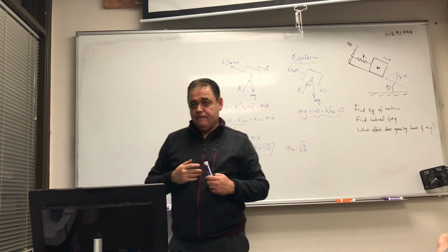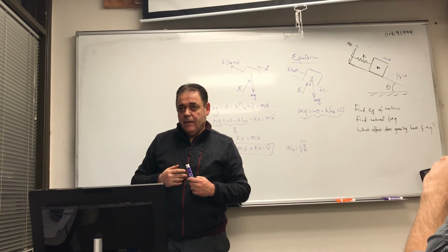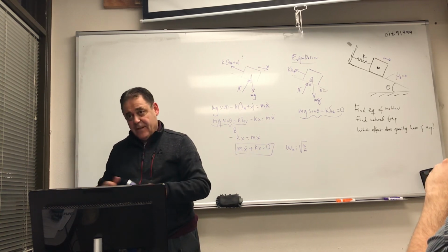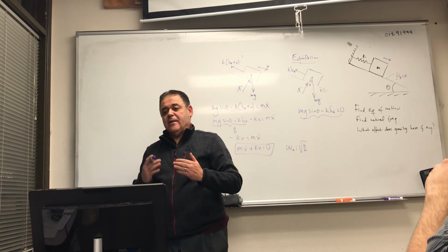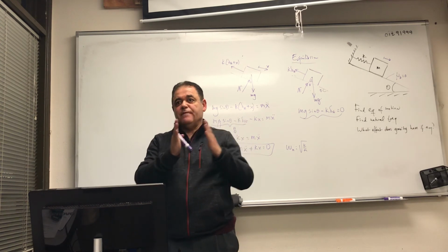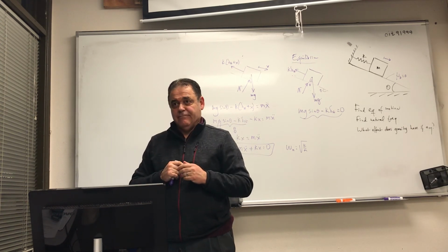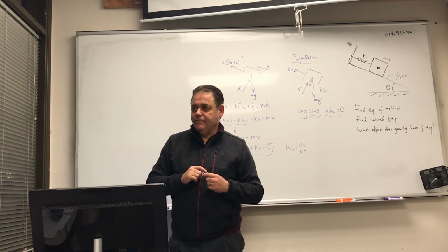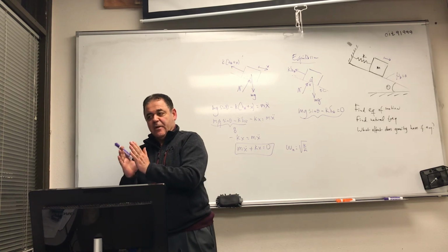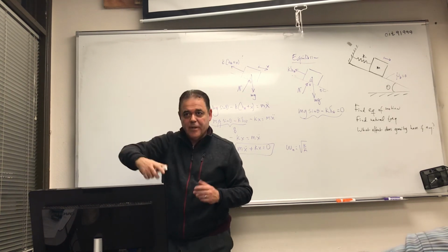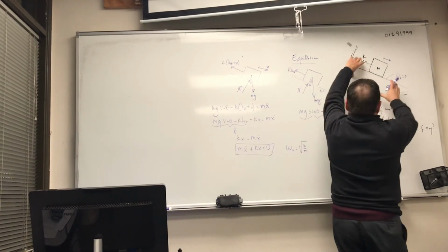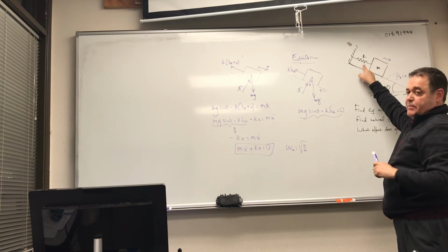So we're saying that gravity doesn't have an effect on the vibrating system, but gravity does have an effect on the static system, right? Because what the gravity has an effect on, just to be more exact, is the shifting of the equilibrium position. Since it's acting constantly, it doesn't make any difference. You're just shifting, so you're taking that part out. Remember that block that we threw in? It's the same thing. You're just shifting the position. Because if theta is equal to 0, what's gonna happen to the spring?